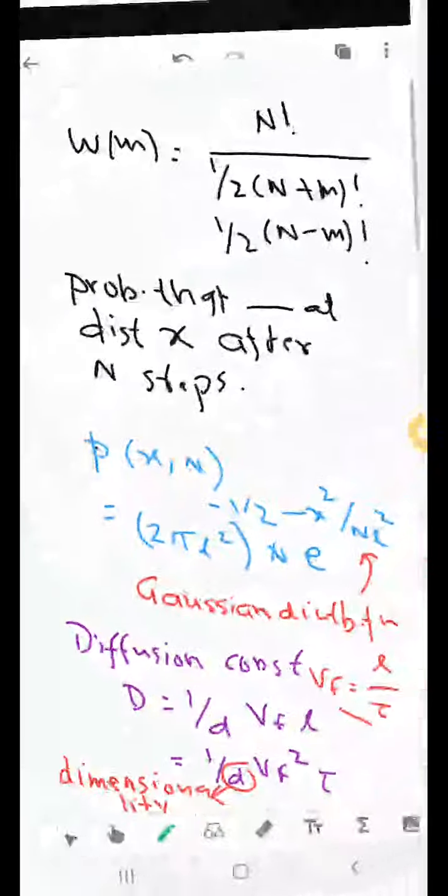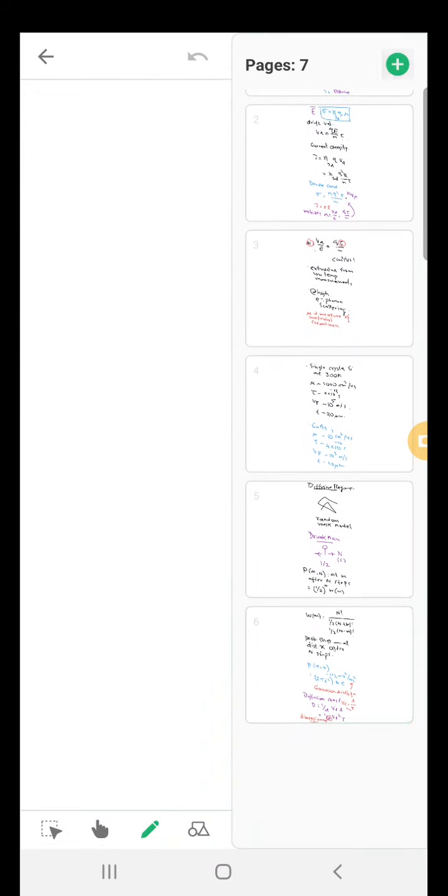It is significant because, if we say that the device or the material where this electron transport is taking place has dimensions length, width and thickness, then the dimensionality will be 3D if all of length, width and thickness are much greater than the mean free path.